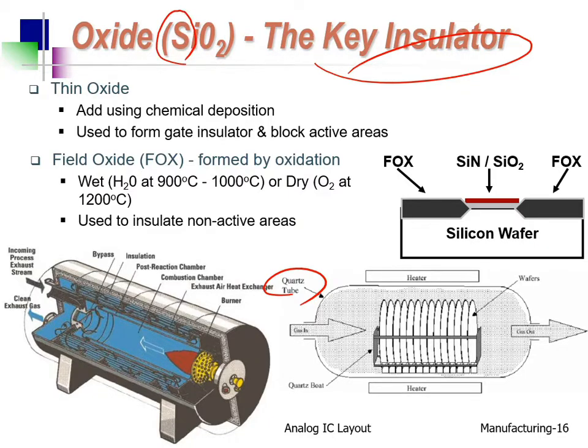If you go outside to pick one rock and watch it for oxidation, how long would you need? Thousands of years. We don't have that kind of time for waiting. We need to speed up the oxidation. But how? High temperature and high density. That's it. So we oxidize many wafers at the same time inside the tube. Here is for oxygen to get in, there to get out.